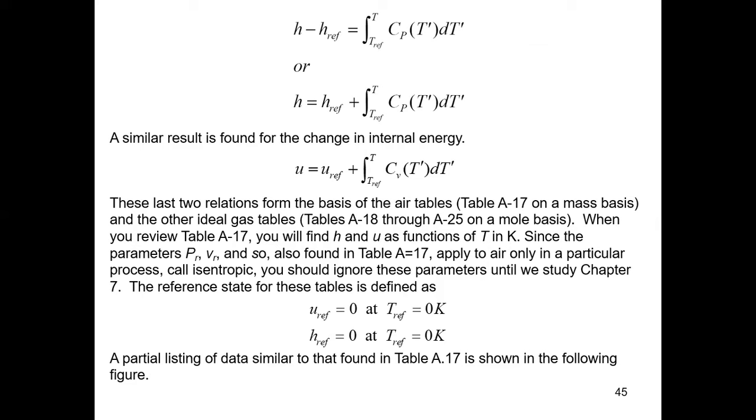And for internal energy, u is equal to u reference plus the integral of Cv(T) dT going from T reference to T. These two relations form the basis of air tables on a mass basis and other ideal gas tables.